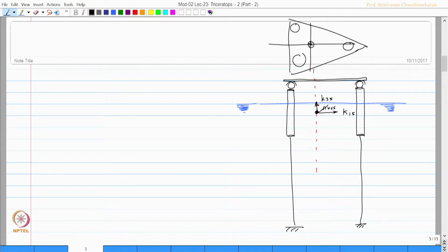The center of buoyancy is located slightly offset for a simple reason: you are giving pitch, which is a rotational degree of freedom. Therefore, there may be a small shift in the center of buoyancy. The shift between these two is the eccentricity, which we call E phi, and the change in tension because of the shift will be indicated as T 0 plus delta T phi.